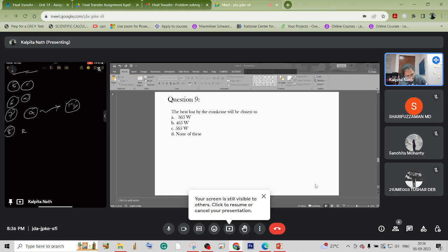First, we will calculate the Reynolds number. So Reynolds number will come out to be 990306. That is greater than 5 into 10 power 5, because it is flow over a flat plate, right? So now for turbulent flow, Nusselt's number is equal to 0.036 Reynolds number to the power 0.8 Prandtl number to the power 0.33. So this comes out to be 2002. That is option B.